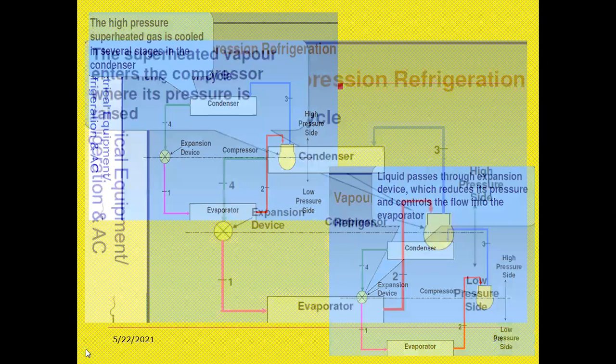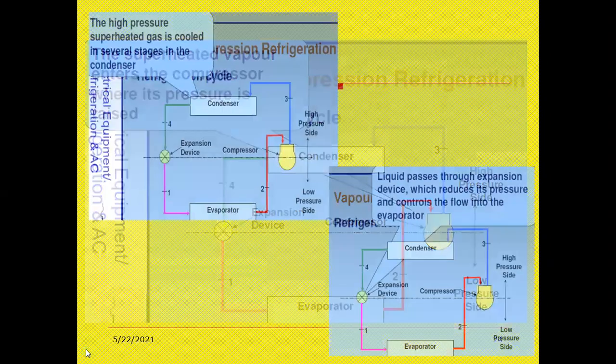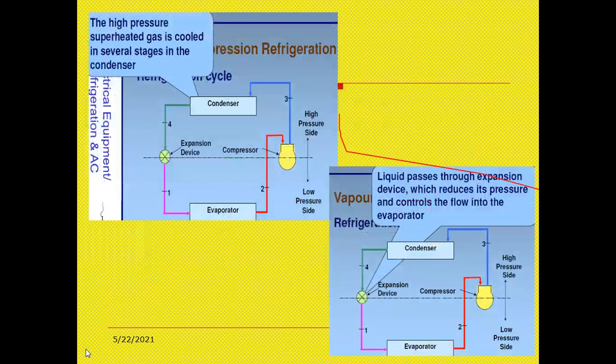So in the compressor chamber, the refrigerant which is converted to gaseous form and stored in the evaporator is moved to the compressor, where the temperature is highly raised. Once in the compressor the temperature is raised, so automatically we have to cool it down by using the condenser process.